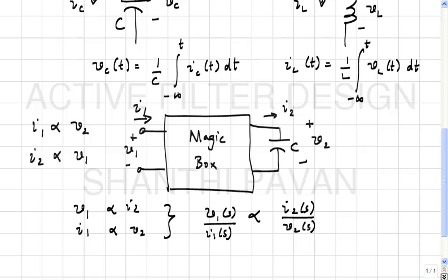Conductance. Similarly, conductance. And obviously, it's not good to call this conductance, because when somebody says conductance or resistance, what do you understand by that term? When voltage and current at the same port are related by some constant quantity, that constant quantity is called either the conductance or the resistance, right? Now the voltage is at one port and the current is at some other port, so what must you call it? Transconductance. Okay, so these constants of proportionality have dimensions of conductance, and you call them transconductances, because they relate the voltage at one port to current at some other port.